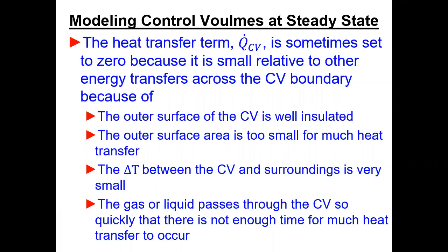So if you're a pound or a kilogram of steam flowing through that thing, what opportunity do you have to lose heat in that turbine to the surroundings? Not much at all. First, it's insulated, and two, you probably spend a millisecond inside the turbine, and you're gone. Now, if you lift that blanket and put your hand on the surface of that thing, that steam's 1,000 degrees. It won't feel good. You won't leave it there long.